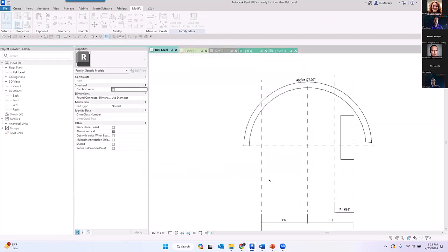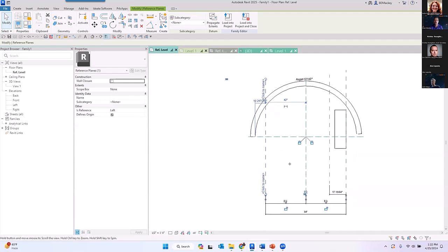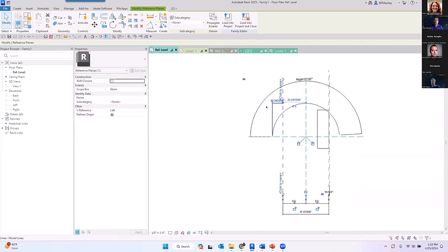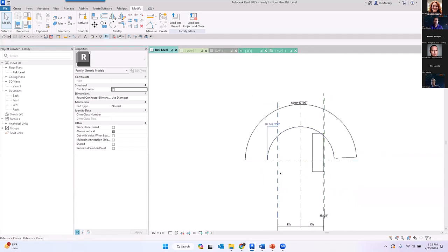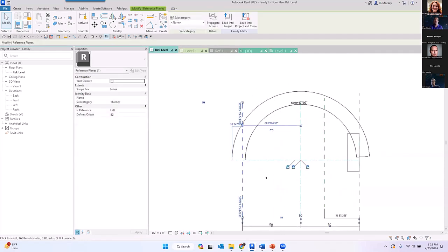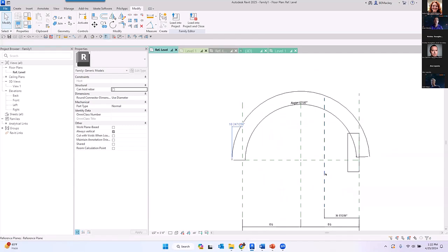If I turn this on, you're going to start seeing that Revit is going to display these automatic sketch dimensions. What this actually means is this is showing you what Revit is not constraining, but associating things to. So the endpoint of this line is associated to this reference plane. If I take this reference plane and move it, that is going to change that line. My line is moving because it has a reference to this reference plane, right? That's where I need to go.